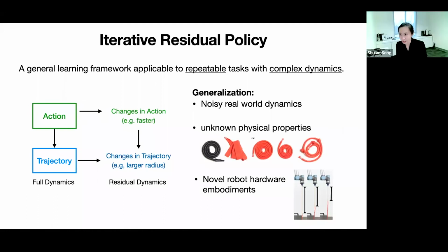Yeah, so actually for the two tasks, we use two slightly different ways to initialize it. For the rope task, given a goal, we use the average action. We have the simulation data, right? We generate many different ropes that we train on in simulation. Then we can compute the average trajectories and compute the average best action that you can use regardless of the rope. And that is the initial action. And for the glass task, we just randomly initialize it with the same initial actions regardless of the goal.